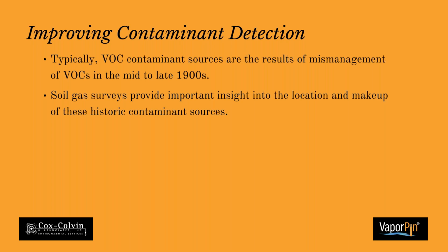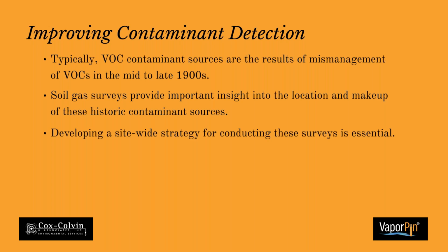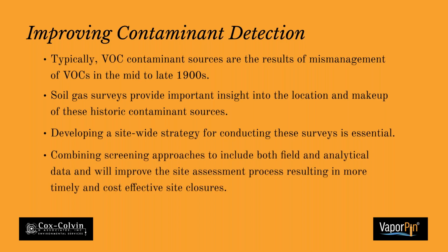Soil gas surveys are important because now you can look for those VOCs still in the subsurface. And if you do a soil gas survey, you don't have to be actually on the contamination, but just close to it. And so you can gain a lot of insight just by doing the detailed soil gas survey to find out where these contamination sources might be. Then you can develop a site-wide strategy for conducting these surveys, and it'll be a very prudent thing to do.